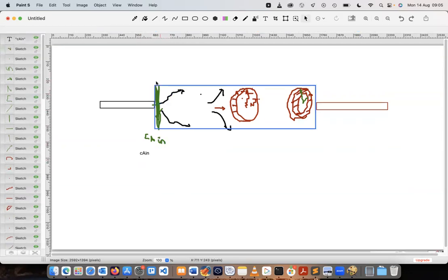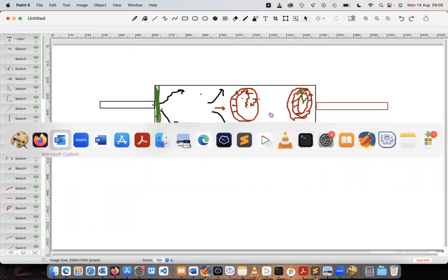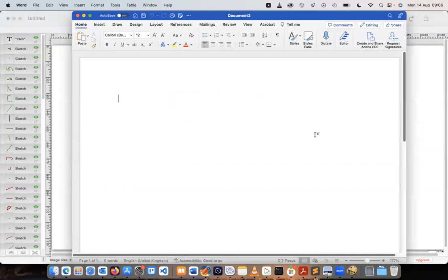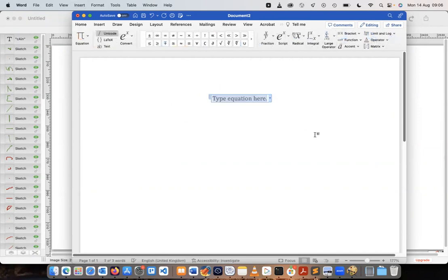Now, to express that in terms of the variables we've been using for the balance, we can simply say that the concentration of A, for all time t, at the z position z equals 0, and for all r positions, is Ca in.